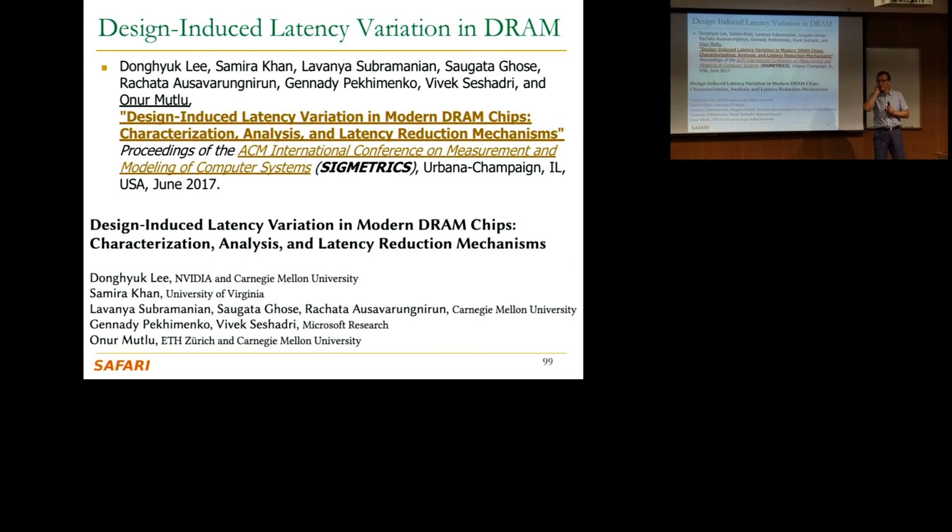I think the reliance on ECC here needs to be studied very carefully. The reason is that you may have an effect where things suddenly go bad. It's not smooth degradation. You go from no errors to too many errors very easily. Yeah, I agree with you. So what we're doing with ECC over here is that the big reliance in terms of reducing latency is this inherently slow region. And we add a margin on top of that.